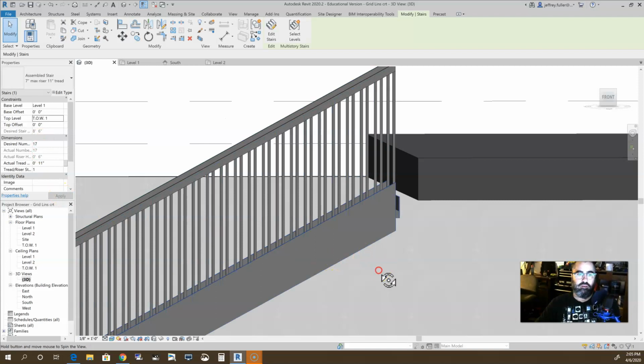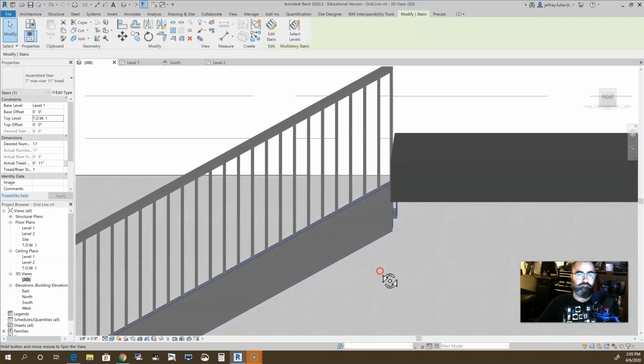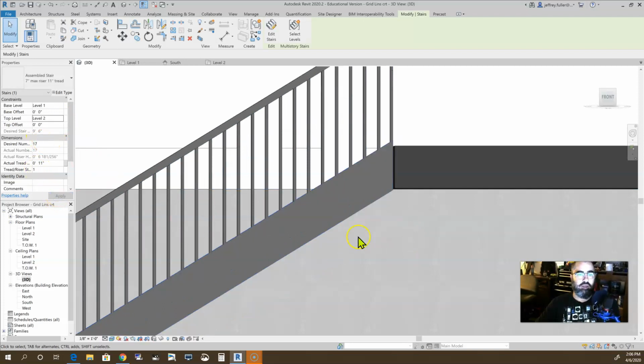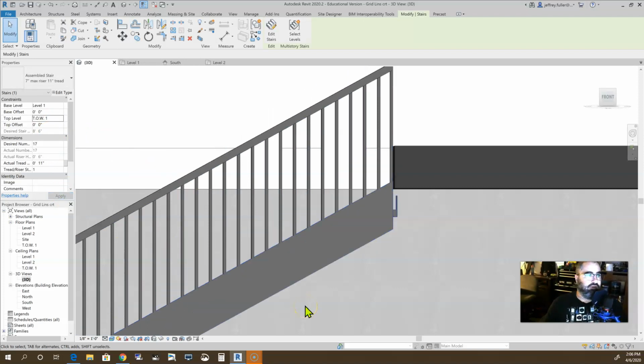It will. Okay, so that's where it would come out if I'd set it incorrectly to go up to the top of wall 1 when I really need it to go to level 2. And if you ran it to top of wall 1, then changed it to level 2, and it still didn't go up any, it's probably because you didn't drag all of your risers out.